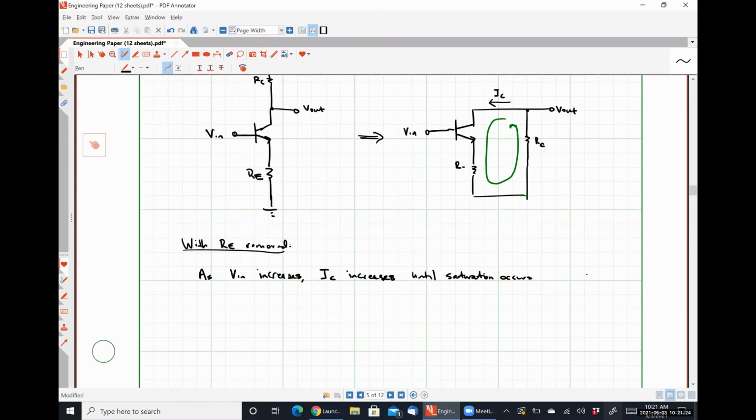Now, at the small scale, for this open loop system, our gain, IC divided by Vn, is simply the transconductance, and our voltage gain, AV, is negative GM times RC. So that resistor RC is really nothing more than the sense mechanism that allows us to view the output signal, okay?